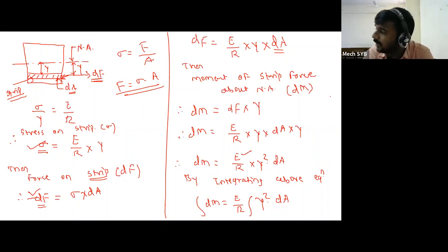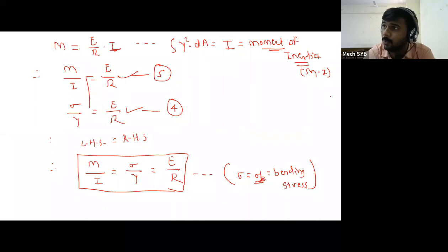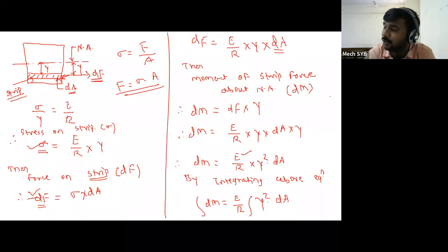What is that y distance? What it represents? sigma माहित आहे आपल्याला, E माहित आहे, R माहित आहे, M माहित आहे. What is the y? No, now here it is y. But if you see the last formula y, so what is that y exactly? What is that y? We need to calculate the CG distance. बरोबर आहे? Y means it is the centroidal distance. Centroidal distance of the section. So you just write down first. I will give the explanation of each and every one at the end.